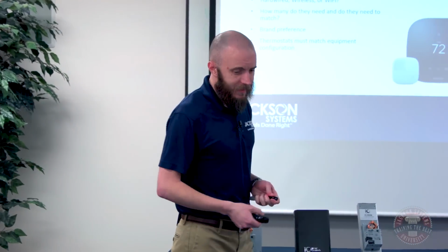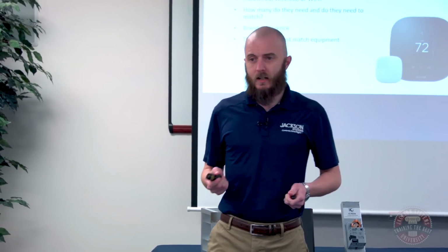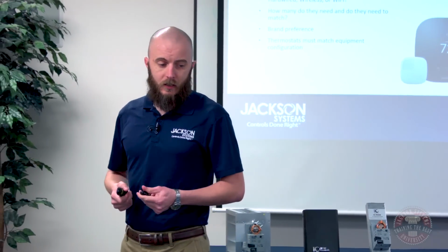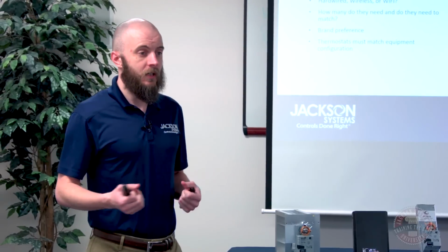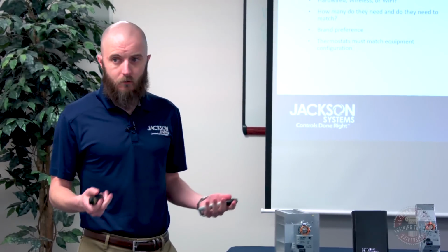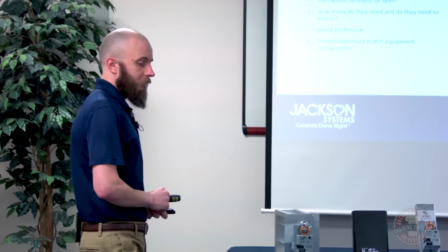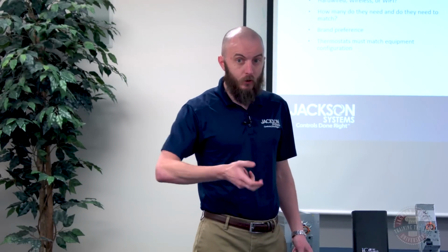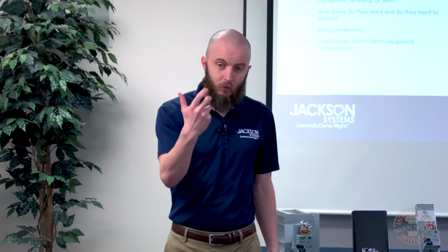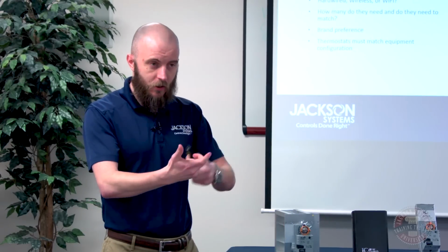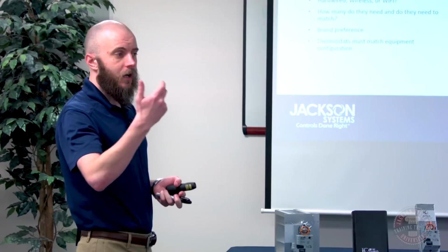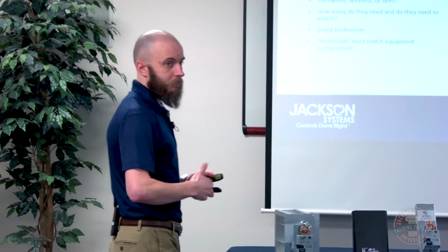Wi-Fi thermostats, again, if you put all Wi-Fi thermostats on a zone system, it's going to give the homeowner a huge degree of control and visibility over their home. Most of the Wi-Fi thermostat manufacturers are going to support multiple devices on their app, so you'll be able to pull their app up on the phone and see all three zones on there, see how the temperatures are doing, control and change set points and everything like that.